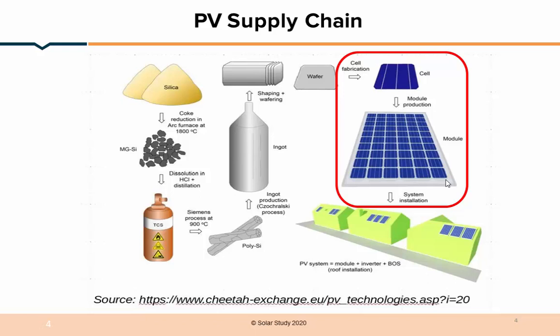You know that monocrystalline is round in shape and multicrystalline is rectangular in shape. Then we get ingots of different shapes. After that, the ingots go to process technology, where a laser cutting machine slices them into small plates, which are called wafers. Then some wafering techniques, laser techniques and doping are done in the manufacturing of the solar cell. They then add grids and bus bars, and we produce the small cell.